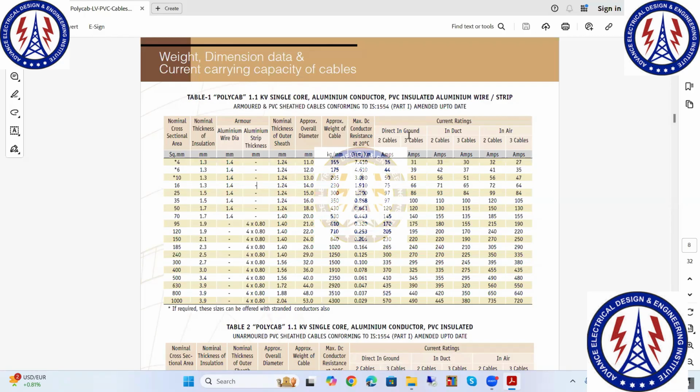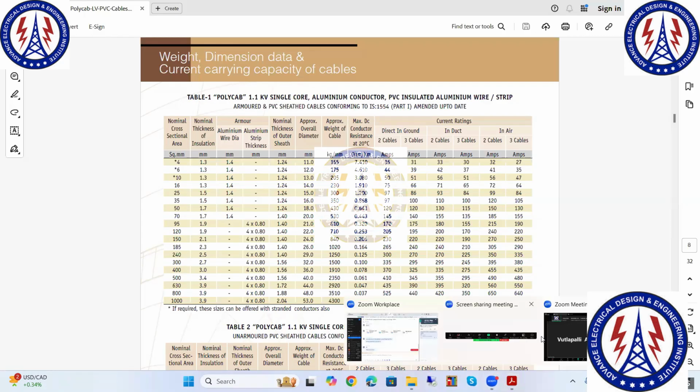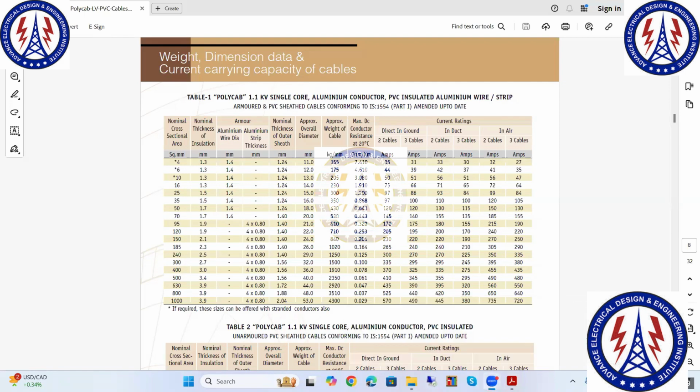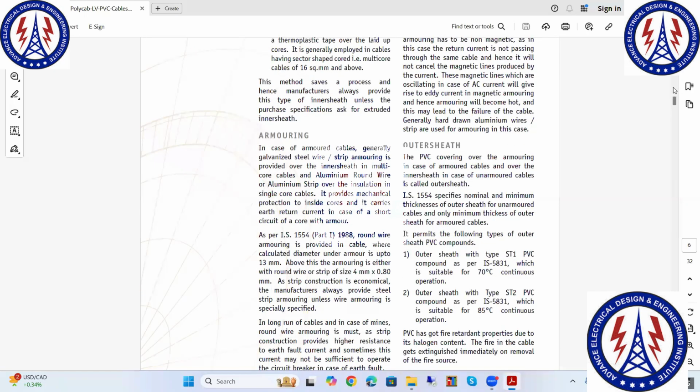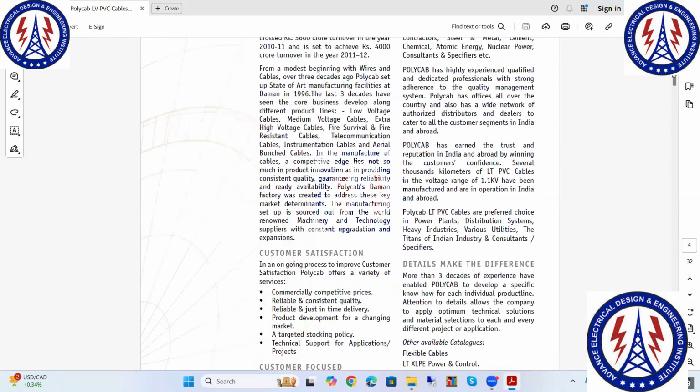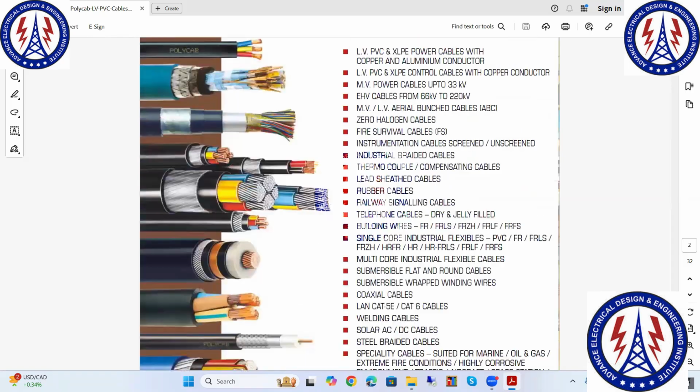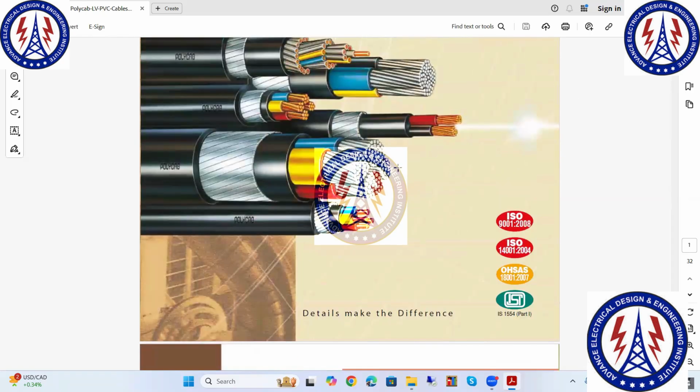Yes, you can ask. I have a doubt. You are telling PVC insulation as well as PVC outer sheath. Yes. In the DC cables, we'll be using only the PVC insulation, if it is a 4 square mm cable or whatever small square mm cables. You are asking about a DC cable, right? DC cable means only two cores will be there, R, Y. Rest thing can remain same. There is no change in the cable.